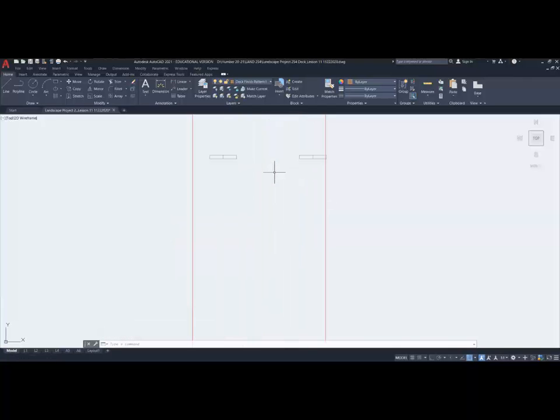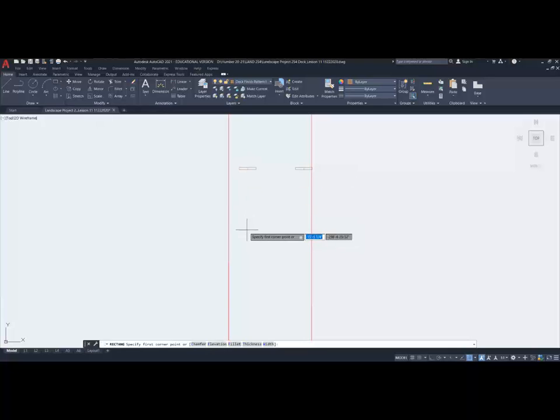Now I'm ready to work on my planter. So the planter, I've decided to make it about 3-foot height. It's going to be 2x6 framing that we're going to be using, and then the deck will be applied to that. I will actually move what I just created down below to this location. So the first thing I'm going to do is create my framing. So that's at 5.5, comma. It's 3 feet tall. I got about 1.5 inches above it, but I'll leave it at 36. That's fine.